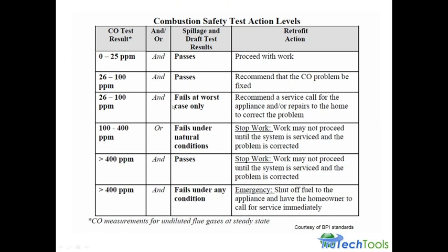26 to 100 and it fails, at worst case, we've got to recommend a service call for the appliance. We're going to get a heating contractor out there and do repairs to the home to correct the problem. 100 to 400 ppm and fails under natural conditions, stop work. This is a dangerous appliance at this point because it could definitely put enough CO into the house to cause